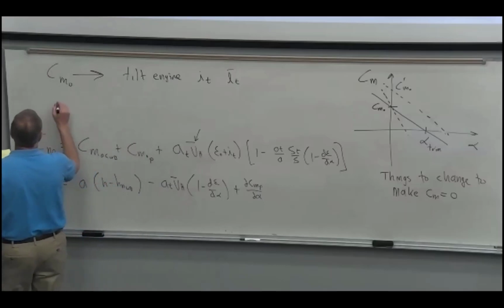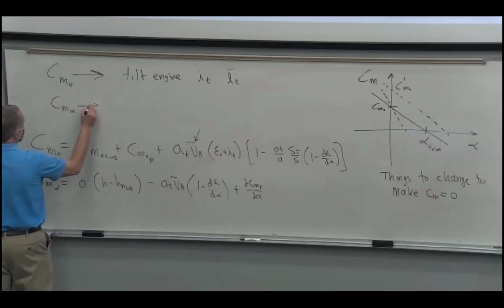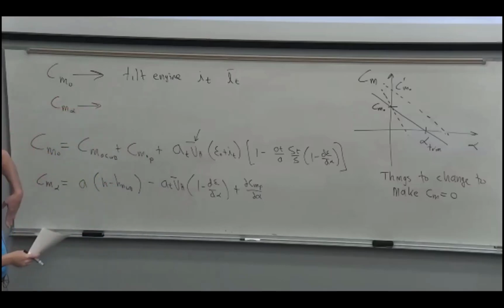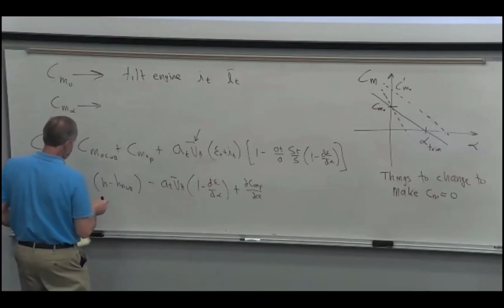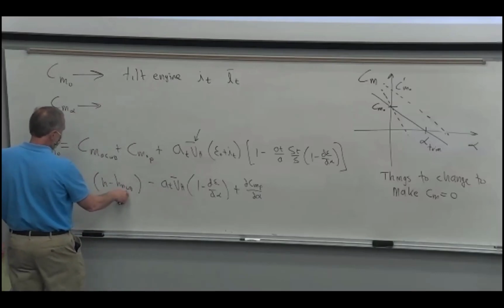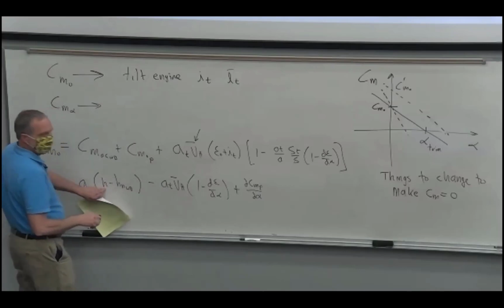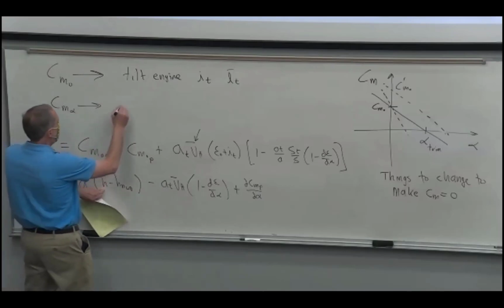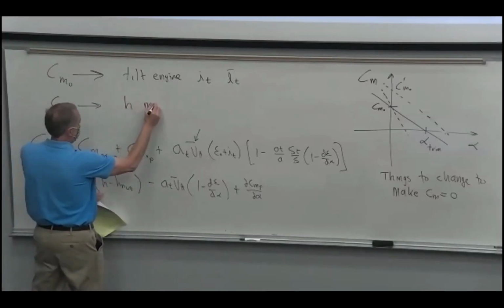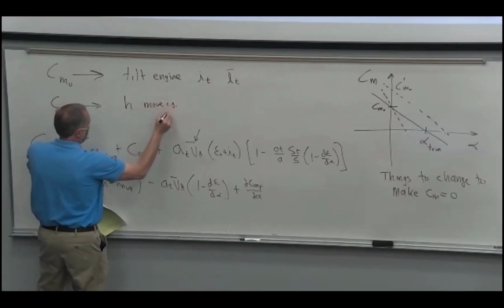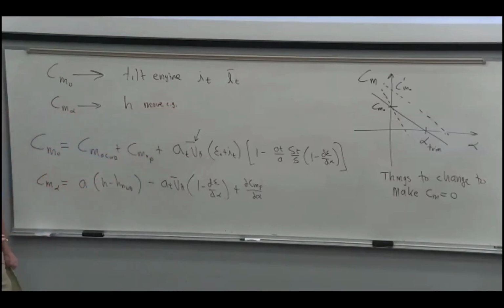And then how about CM alpha? Because if we want to tilt the slope, then we can control where CM alpha is 0. So we look at this formula. Neutral point of the wing body is pretty much fixed, so is the lift curve slope. But we could certainly move the CG around. I mean, actively, not just load cargo and the CG shifts because of how we load it.